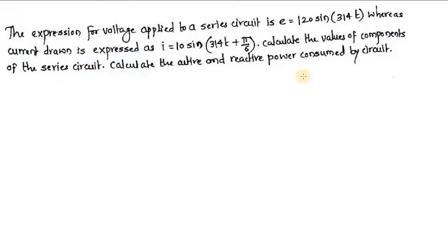We know current is leading by some angle between 0 to 90 only when the circuit is a series RC circuit. So it is very sure that the circuit will consist of a series connection of one resistor and one capacitor.